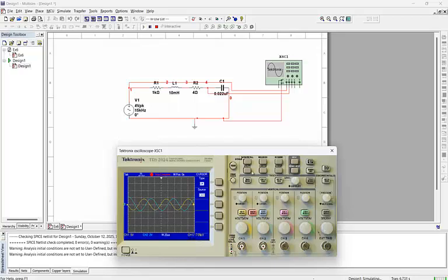Right now I am going to use the cursor. If you activate it, choose type instead of voltage, which will give you a cursor for the y-axis, but we need it for time, so it will give us a cursor like this. So I am going to manipulate it and get another cursor and put it on the second peak.